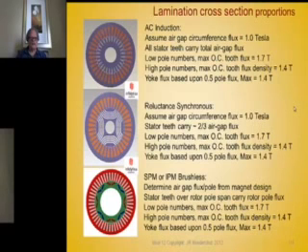Now, for low pole numbers, the maximum open circuit tooth flux density in a brushless motor would be 1.7 Tesla. Of course, we don't exactly have an open circuit situation with flux. In an induction motor, if you have open circuit, there's no flux in the machine at all. But if you have a high pole number in a PM machine, your open circuit tooth density would be in the neighborhood of 1.4.